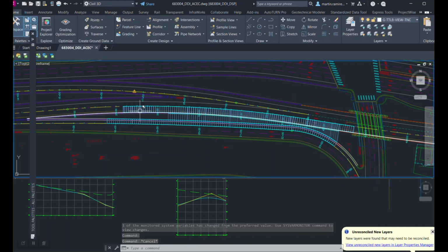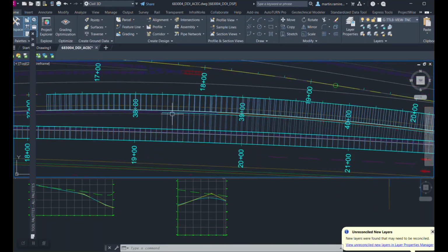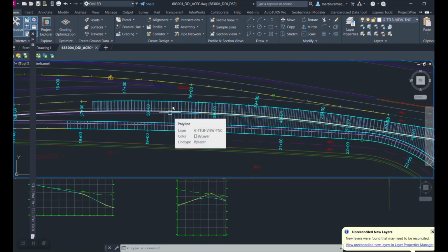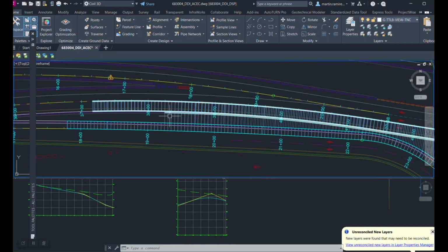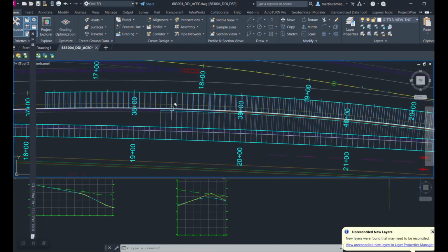And it was very easy to keep track of that, and then also pass on that wall height by extracting the feature lines from the top of the wall, and just letting the wall design team know, all right, that's like the minimum that you have to hit. And it was just a lot quicker and more simple, and I think a lot more accurate, because you're not just tracing things at this point, it's actually calculating it at that specific station, what the height has to be.